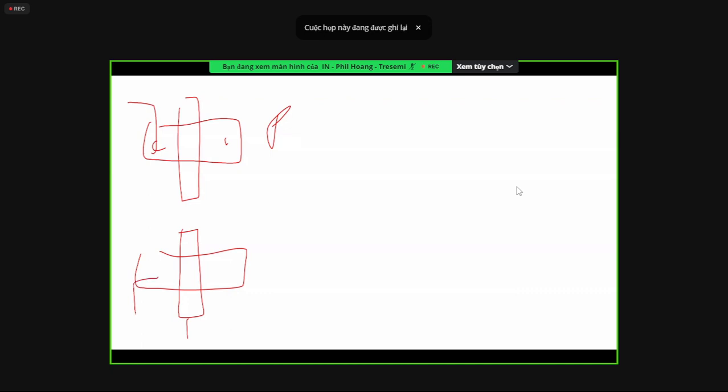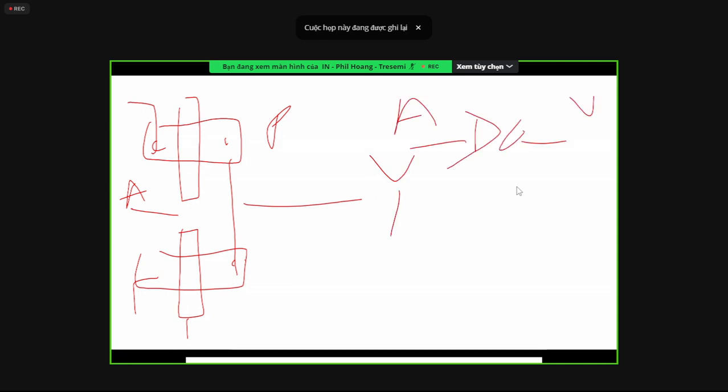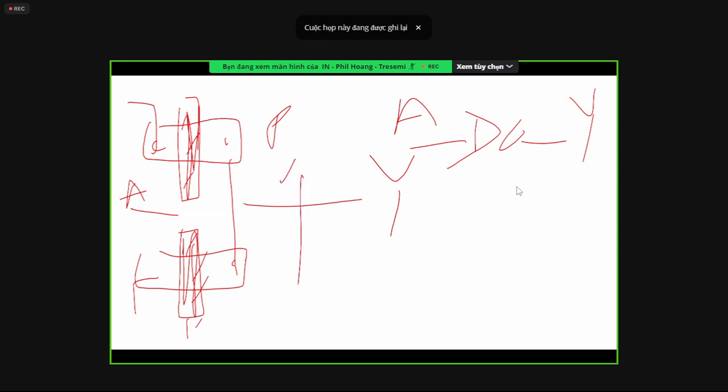This one is connected to ground, and then you have the input coming in, A, and you have the output connected here, so you have a Y here. So this is an inverter, right? So the gate of the inverter is really the poly, right? So these things are going up and down. So this poly orientation is vertical, right?